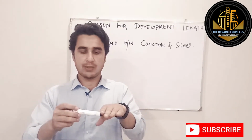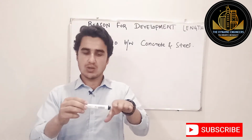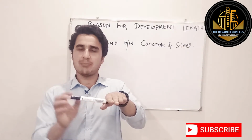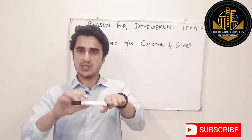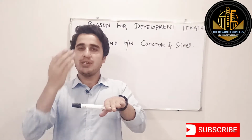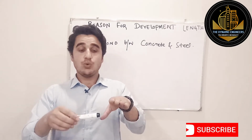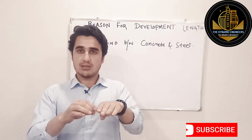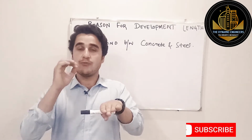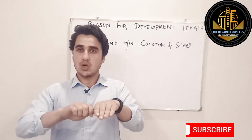Just look at this. This is a steel bar which is embedded in this concrete member. A very small piece of this bar is embedded in this concrete, and if you just pull it, it will just pull out with a very small force. But if you embed a large part of this steel bar in this concrete, then a huge amount of force will be needed to pull out this bar from this concrete member.